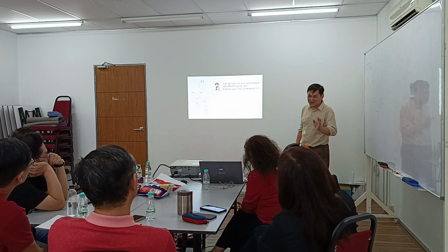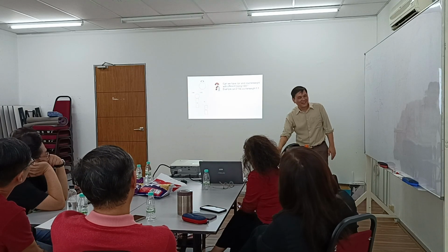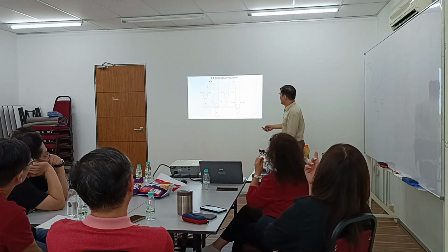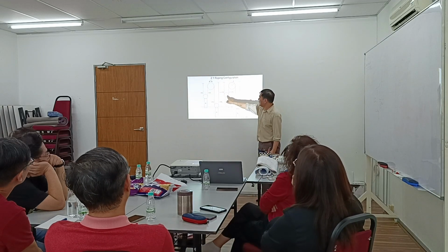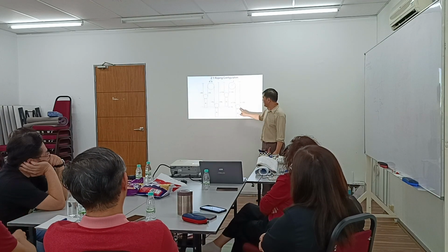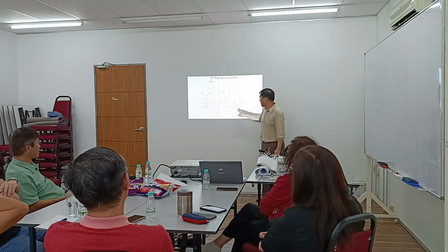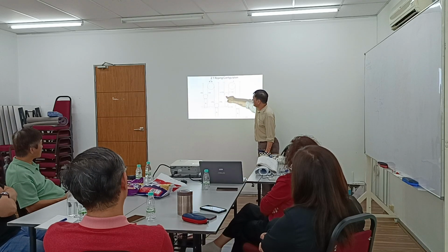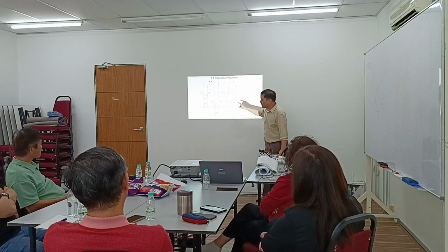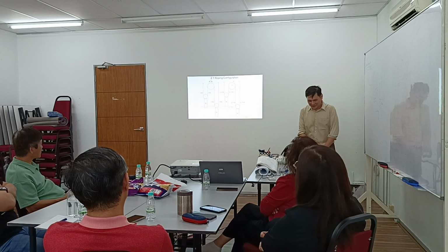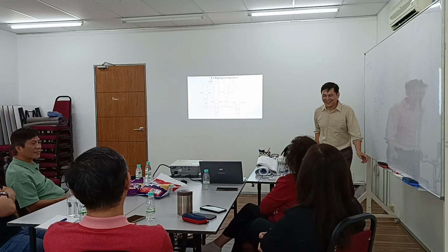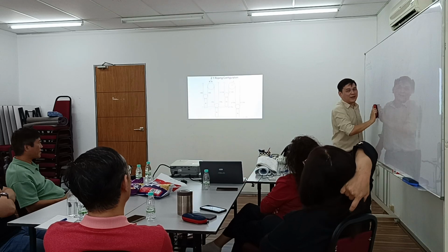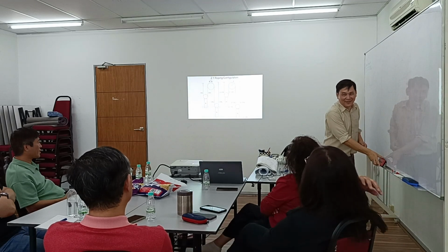It's actually very common sense. Okay, this is 2-to-1, and when I have the pulley, this is also 2-to-1. We have the pulley on the car and counterweight. If let's say I remove the pulley here and directly attach the rope to here, the car becomes 1-to-1 but this one is still 2-to-1. Can or not actually? No, I cannot. No balance, because one will run faster than the other one.